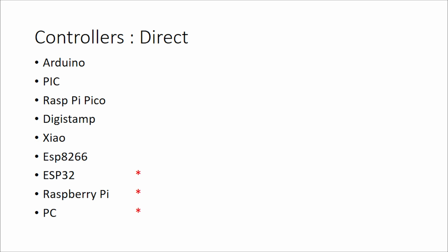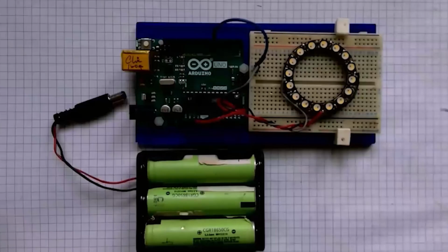So what does it look like? There's an Arduino Uno, 16 megahertz Atmel 328, as we're all aware. So 16 megahertz is plenty of speed for driving these. There's 16 NeoPixels in a ring. 3 wires, as you can see, a red wire, a black wire and a grey wire. Red wire, 5 volts. Black wire, 0 volts.